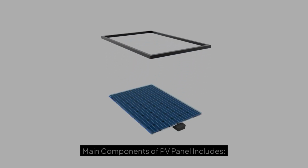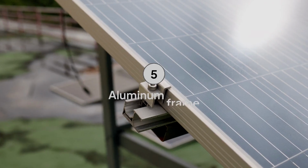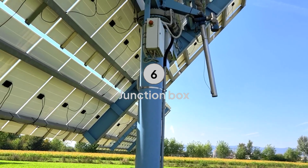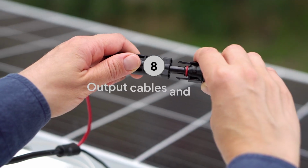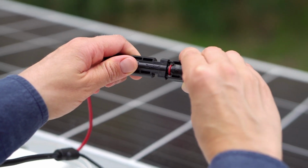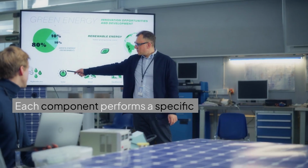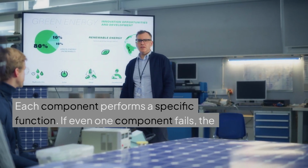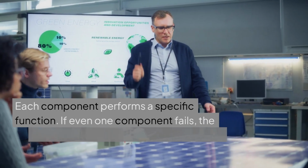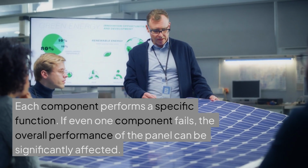Main components of a PV panel include tempered glass, EVA encapsulant, silicon cells, backsheet, aluminium frame, junction box, bypass diodes, output cables and MC4 connectors. Each component performs a specific function. If even one component fails, the overall performance of the panel can be significantly affected.